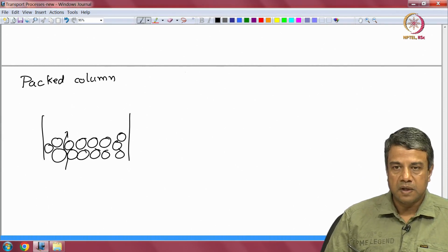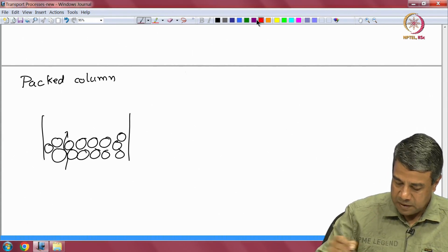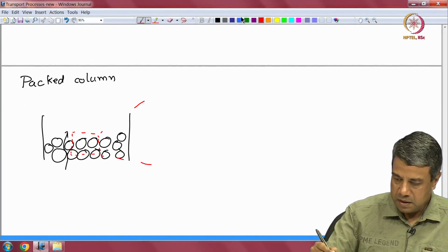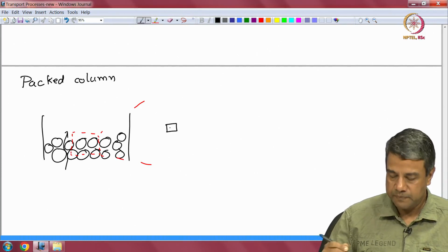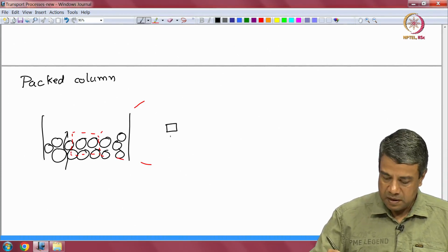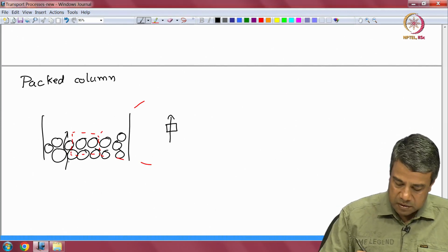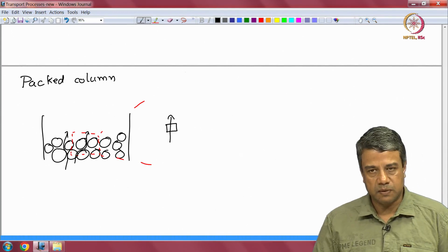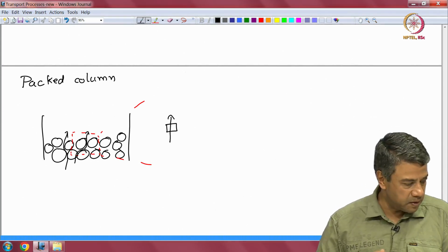If you make an average description where you include a length scale that is larger than the particle size, as an effective medium, then you have an effective velocity through, but you also have these velocity fluctuations as the fluid traverses tortuous paths between the particles.